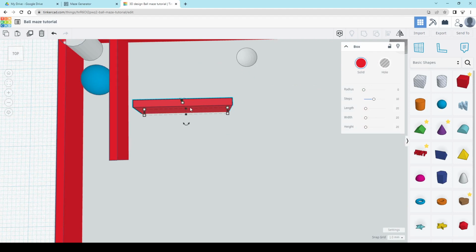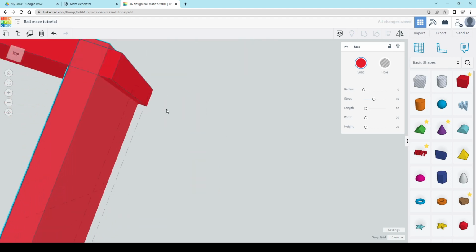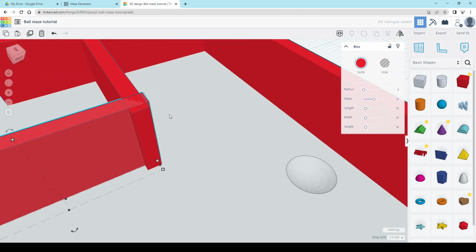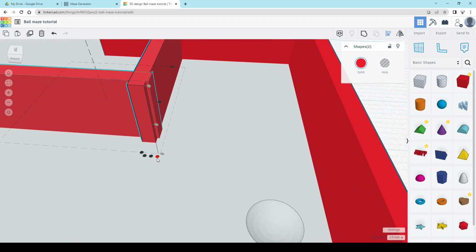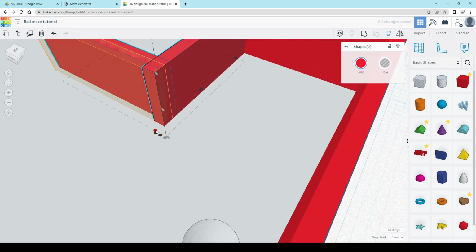Just one little tip, just in case you missed the first time. This is how you duplicate the wall. So clicking on the wall, Control D for duplicate, and then if you rotate this within the circle, it will snap to the common degrees. You're only going to be using 90. And you could also use the align tool, which is, I'm going to select both of these, align it. I don't want this one to move, so I'm going to click on this, and it will preview where it will align to, like that.